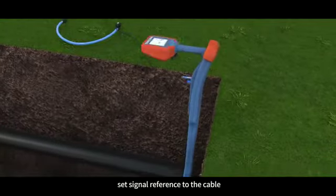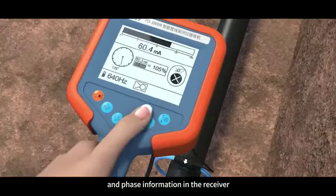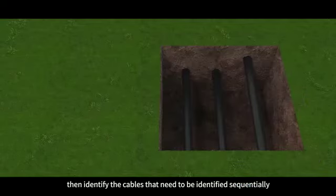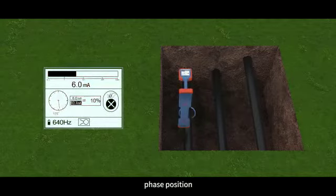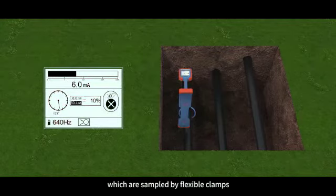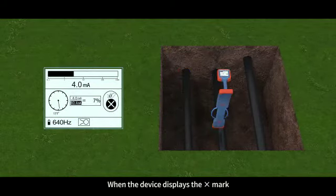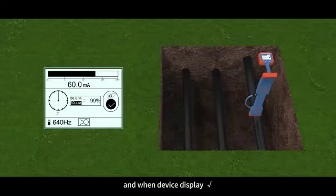Firstly, set the signal reference to the cable at the signal transmitting terminal. Then store this current amplitude and phase information in the receiver. Then identify the cables that need to be identified sequentially. The receiver will compare and distinguish the current amplitude, phase position, and frequency sampled by the flexible clamps from the cables to be identified, and give an accurate identification result. When the device displays a cross mark, it is a non-target cable, and when the device displays a check, it is the target cable.